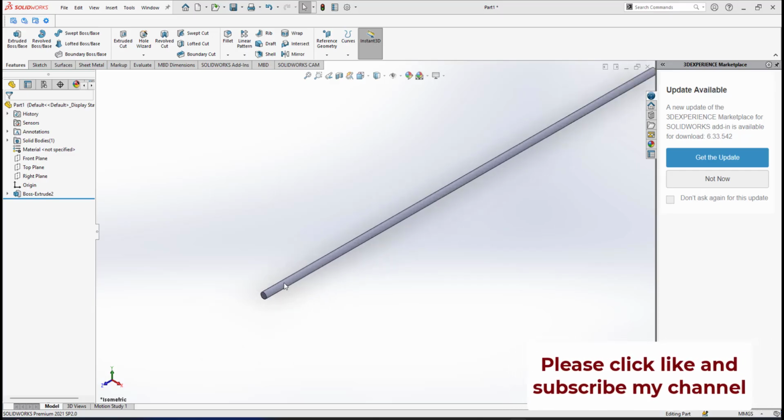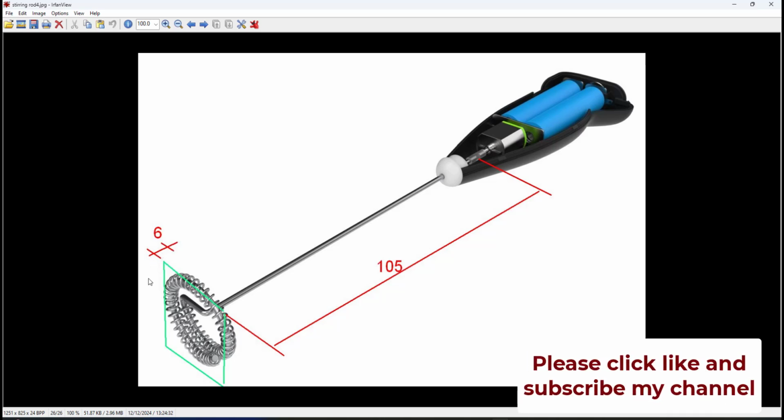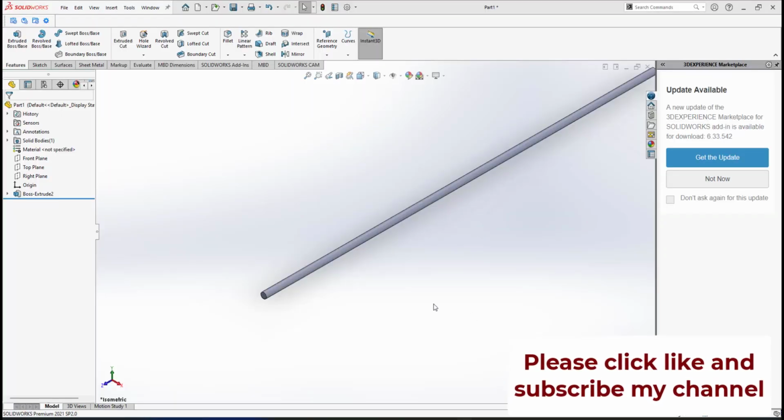At the end here, we have a helix shape, as shown in the image, a helix or spiral. To do that, I need to create a plane at a distance of 6 from the end of that straight rod. I need a base shape to create this helix or spiral, which is a circle.